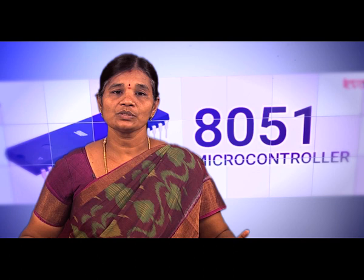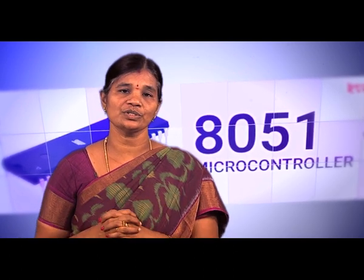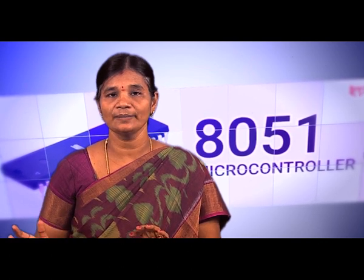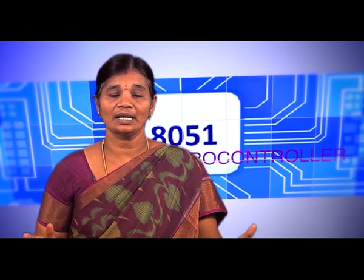Okay. And in case of BCD addition, you have to adjust the decimal position by adding 6 when it exceeds 9. So, one of the special instructions we have is DAA, which will adjust. The same thing, DAS, is also available for the decimal adjust after subtraction. Okay. So, I hope you understand how to add 8-bit data and 16-bit data by using the 8051, right. Next, we will discuss the logical instructions along with the signed and unsigned additions. Thank you.